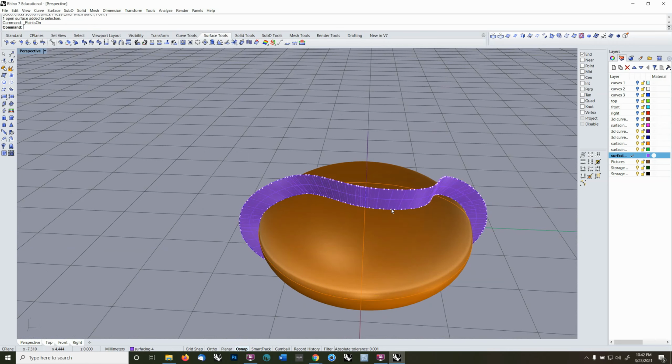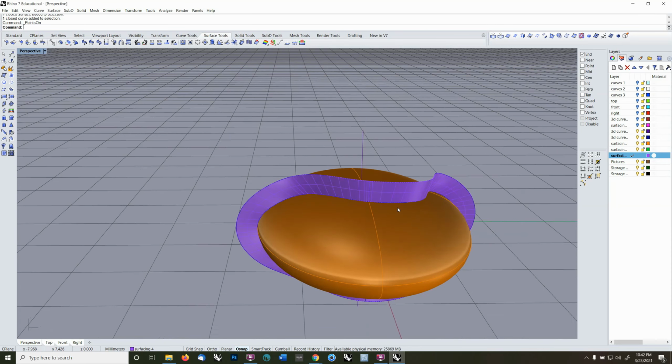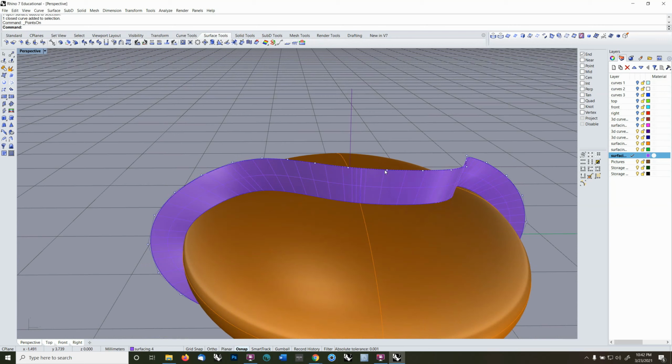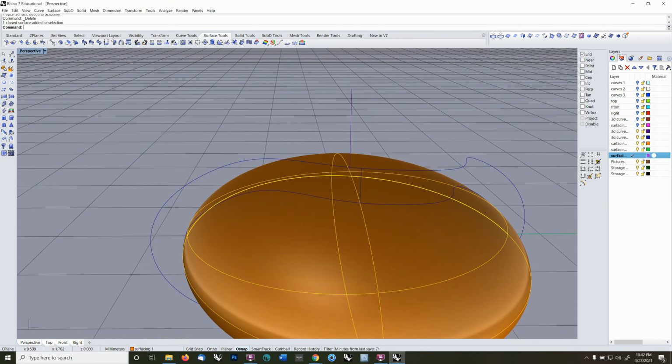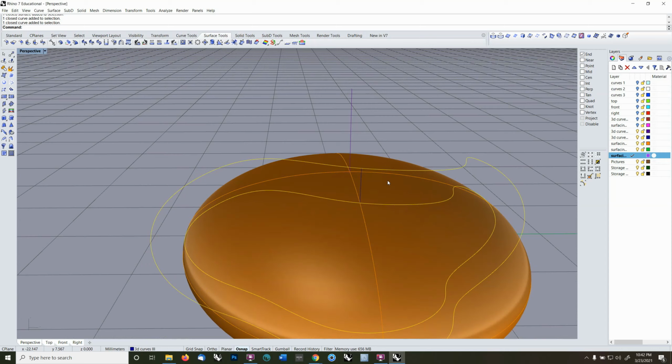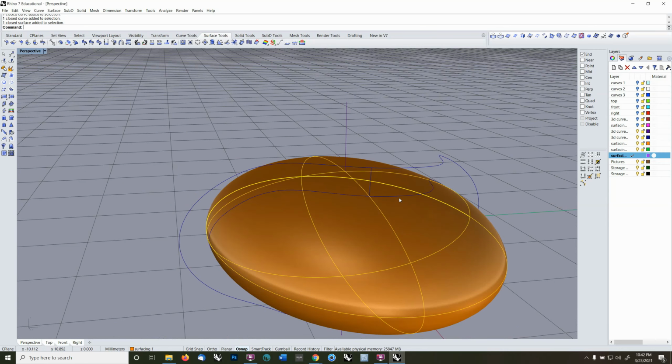And this should have picked up the cross-section, the control points from these two surfaces. It didn't. Loft will, so that's kind of, don't like where the seam was before, so I'm going to move the seam in the curves.